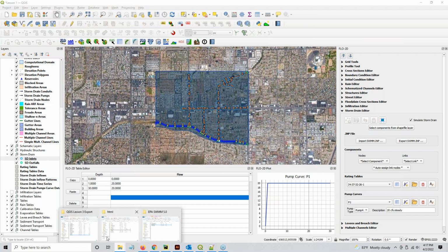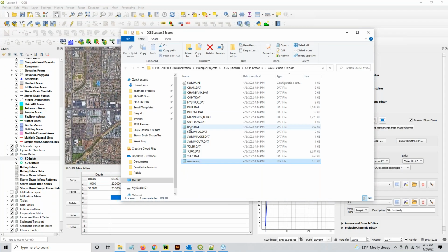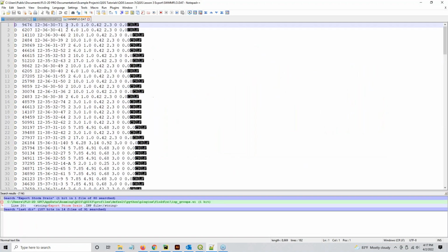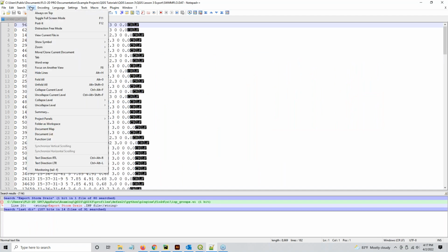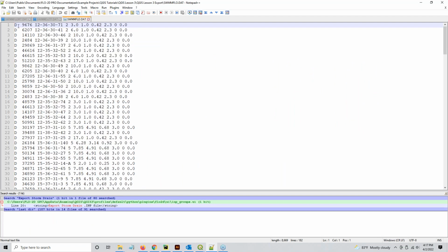All right, let's get back here for a sec. Okay, so we also have these 3 files, and this is the data related to Flow2D. I'm going to open that in Notepad because there's 3 of them. And I will turn off the end of the line symbols because we don't need to see those. So these are the inlets that connect to the surface. This is the grid element they connect through. This is the inlet name, and this is the inlet type, and these are the geometry and weir coefficient, and other switches you might need for that.